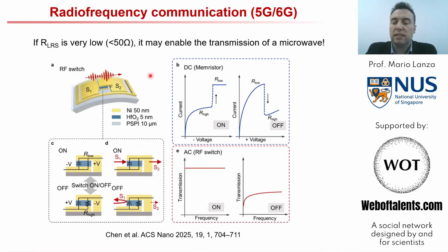And this is very interesting because state-of-the-art radio frequency switches are normally very big, and the memristor here has a very important opportunity to replace them. The main challenge in this field is endurance, because switching with very low resistance is something a little bit complicated and dangerous, and the structure of the insulator can be damaged. But important progress has been done in the past few years.